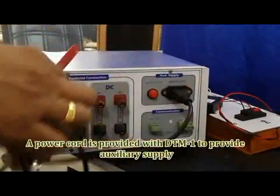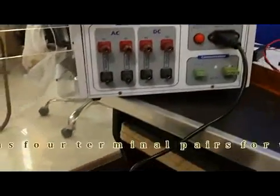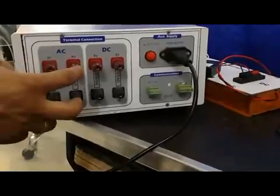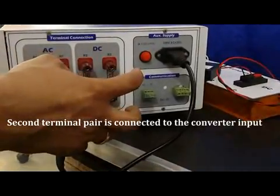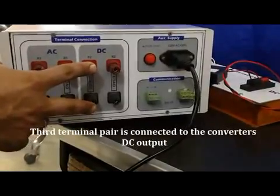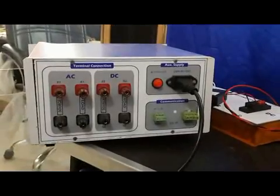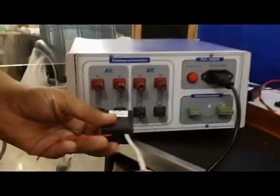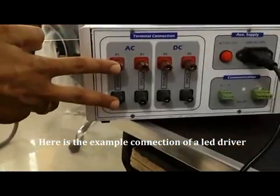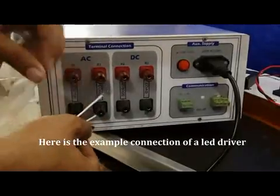Connection diagram for DTM-1. Normally what we use is a power cable. A standard computer power cable is used here to power the auxiliary supply of 230 volt AC. We also have two wires coming in for AC parameters and two wires coming out to the LED driver, as well as two wires coming in for the DC parameters and two wires coming out for the DC parameters.